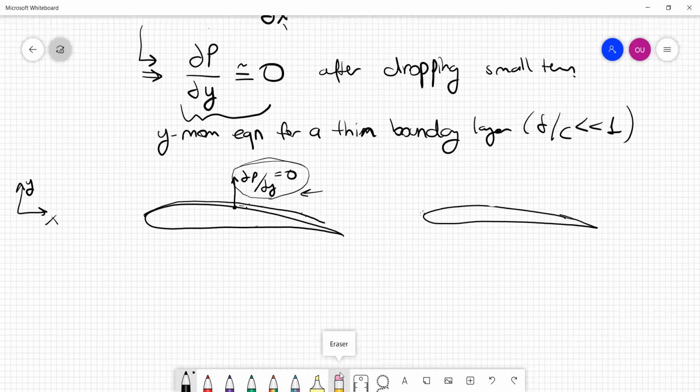Generally, we will see those later, but the boundary layers start as what we call laminar boundary layers. They go through transition, and then suddenly the boundary layer thickness increases a lot to a turbulent boundary layer. If this is the case, the inviscid solution will have to be modified slightly. And I'm still saying slightly. I mean, you do not have to have a major change.